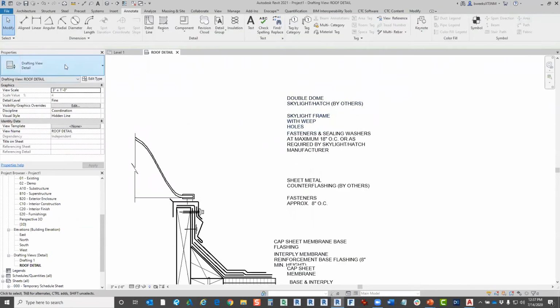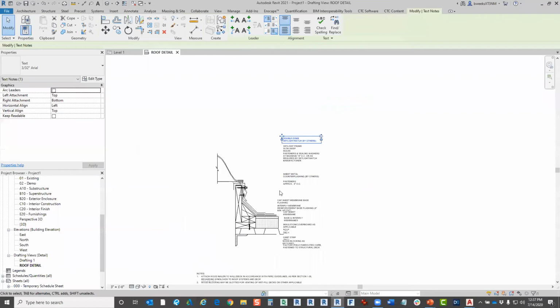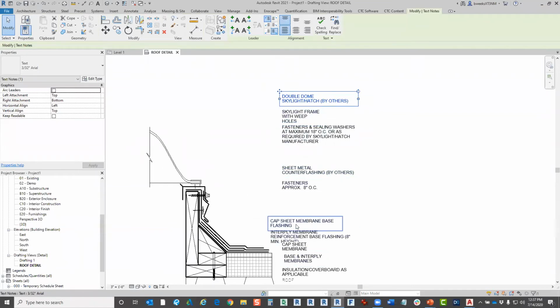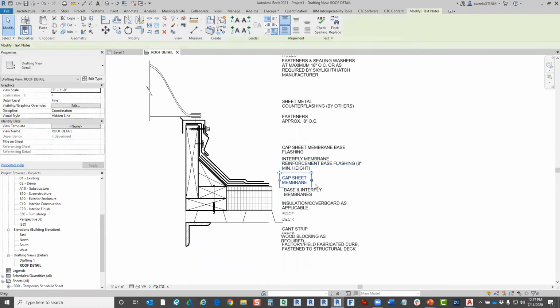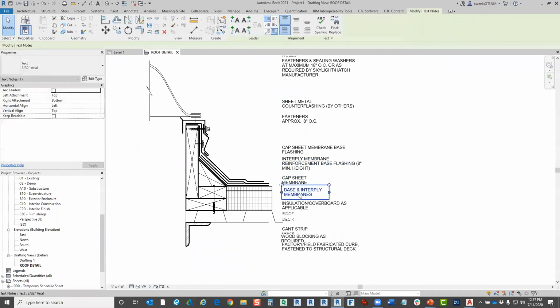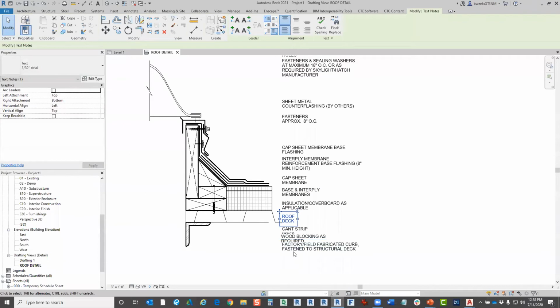3/32nd out of the box with Revit is the standard font size, so that when you scale details, the font scales appropriately, and that's typically a good readable scale for the font. If you have titles and things like that, you can of course change those as you need to. But again, I'm just trying to show you some best practices.